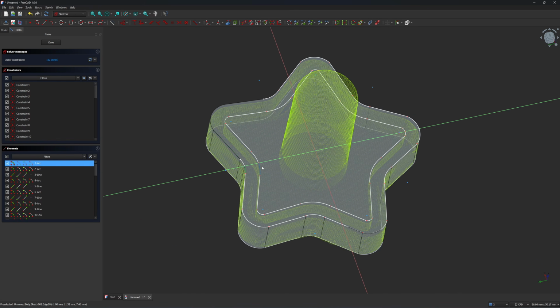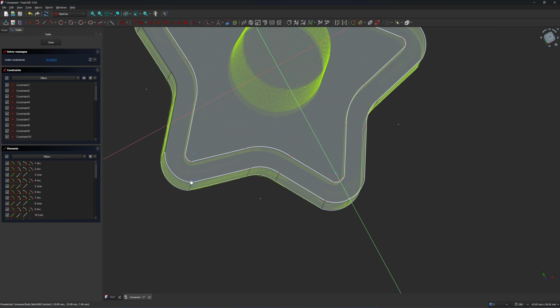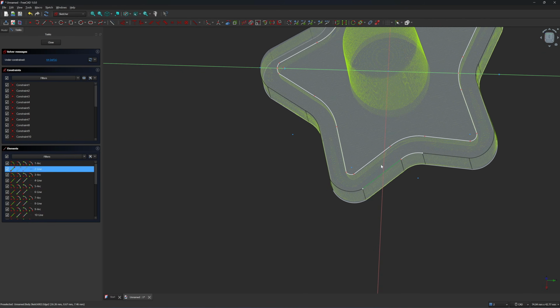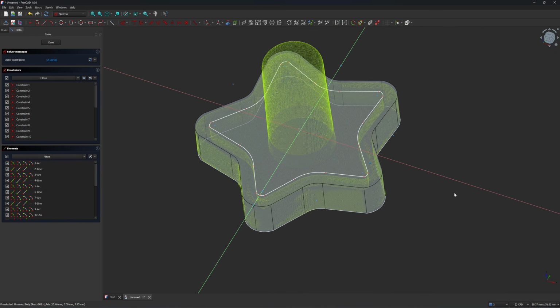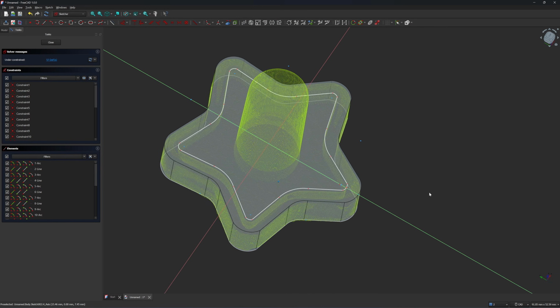You need to delete it. I don't know why I have to do this, but in Autodesk Inventor I don't have to, because when you do extrude cut, you can choose which sketch to cut with. In FreeCAD, it can contain only one sketch. So this will be the closed loop sketch for cutting.